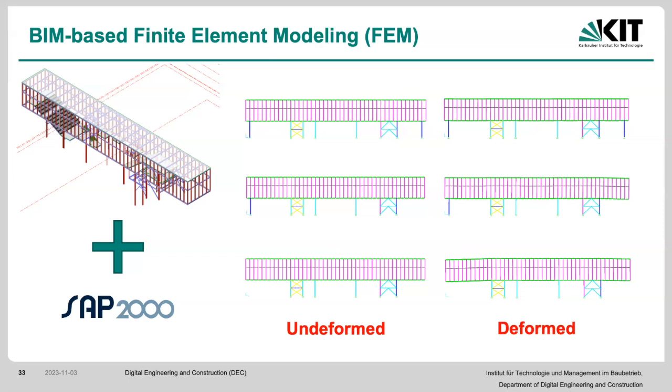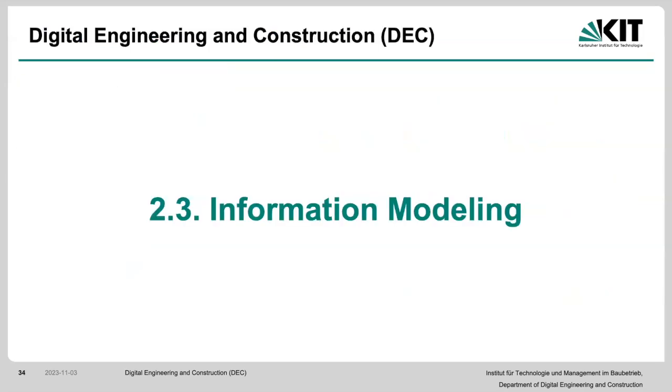They needed to know this way in advance to make sure that whatever window they're going to order or have already ordered is going to properly and in a stable way attach to this, so that the load is not going to increase, let's say, the deformation of the window, because the window is not supposed to be taking the load, right? That's the whole idea. But through that, for instance, I utilized SAP 2000 and did some analysis there. In order to do that, we needed to collect some point cloud data to know what the real displacements are and what the analysis is providing, and then see if they comply or not, okay?